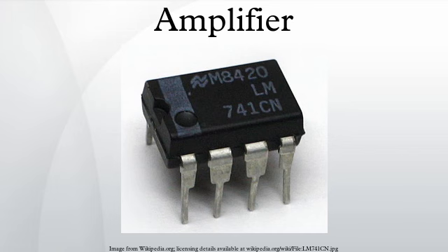The current is in phase with the voltage applied to the filter, but the voltage across the transistors is out of phase. Therefore, there is a minimal overlap between current through the transistors and voltage across the transistors. The sharper the edges, the lower the overlap. While in Class D, transistors and the load exist as two separate modules, Class F admits imperfections like the parasitics of the transistor and tries to optimize the global system to have a high impedance at the harmonics. Of course, there has to be a finite voltage across the transistor to push the current across the on-state resistance.